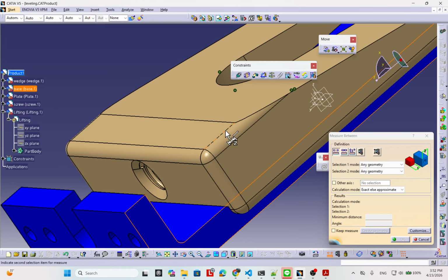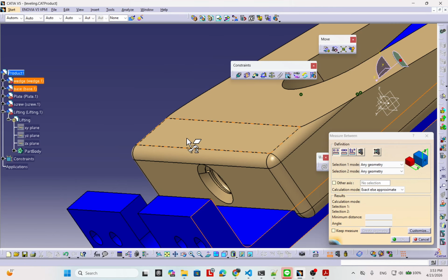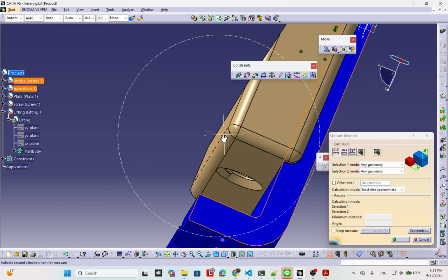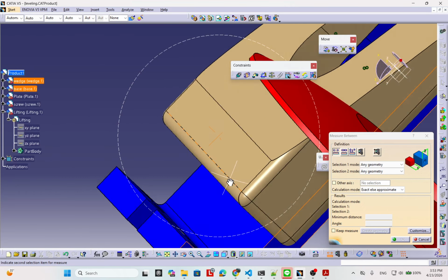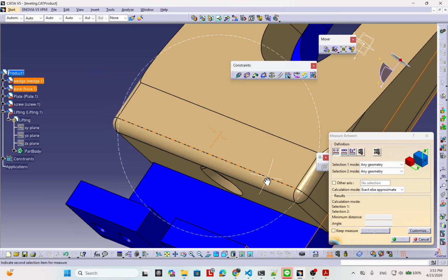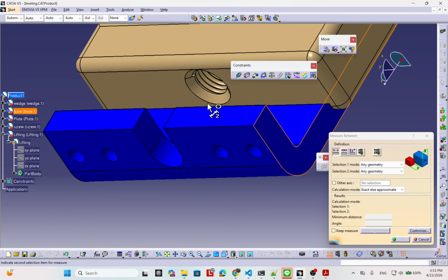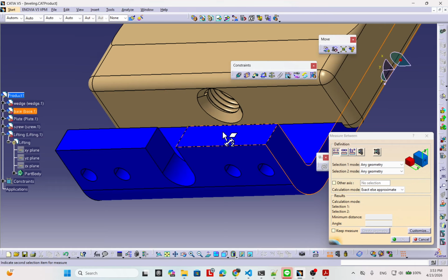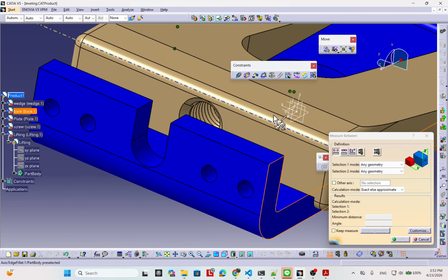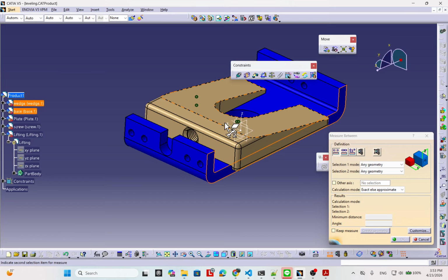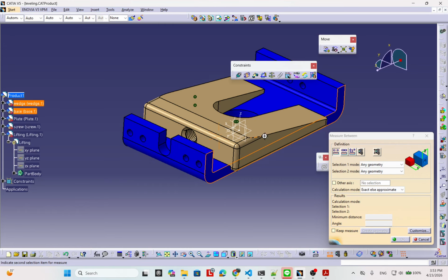If I need to, I click here and set this as the center of rotation. I click the middle mouse there, and you see the orange center has changed. If I need it here, I click middle. You remember this technique to control the 3D view by mouse.